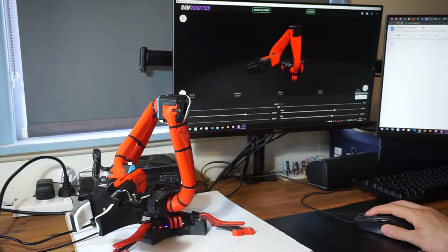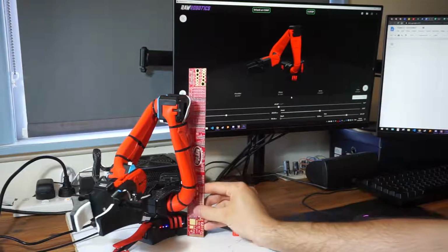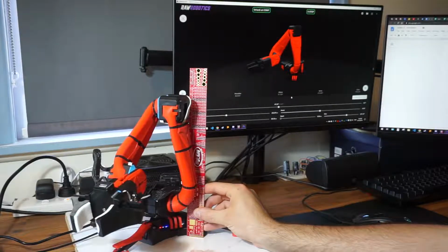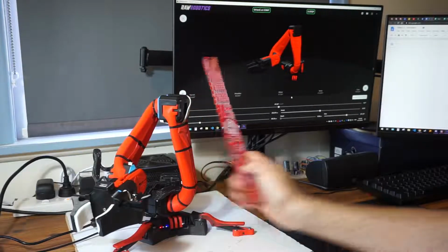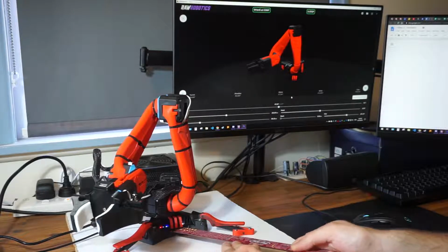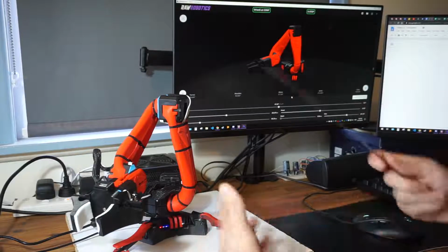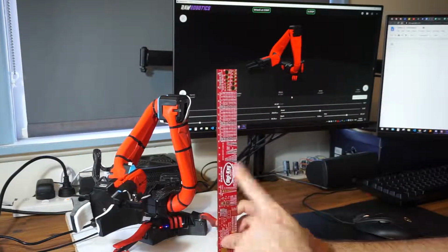Okay, let's change to tool point control mode, and let's see how our original 6 controls work on the real robot. Note that the robot is approximately 15 millimeters off the surface of the table right now. So these heights are all relative to the bottom of the base of the robot. But because that base is about 15 millimeters off the ground, we have to add 15 millimeters to anything we measure relative to the ground.